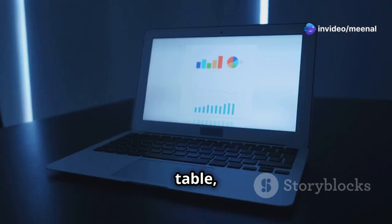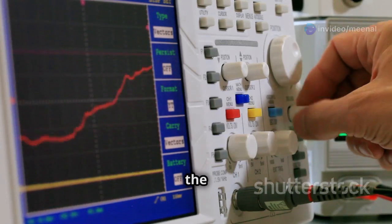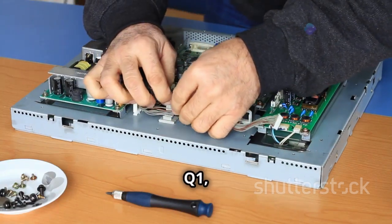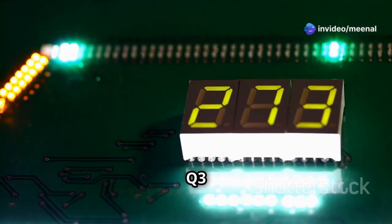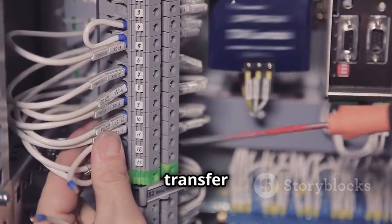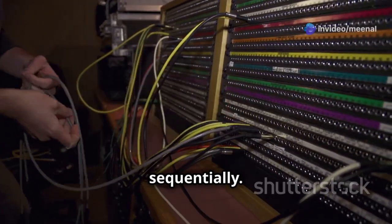In this table, each row represents a clock cycle. The input value is shifted into the first flip-flop, Q0, on each clock pulse. The previous value of Q0 is shifted to Q1, and so on. The value of the last flip-flop, Q3, is the output of the register. SISO shift registers are commonly used for data storage and transfer applications, where data arrives and is retrieved sequentially.